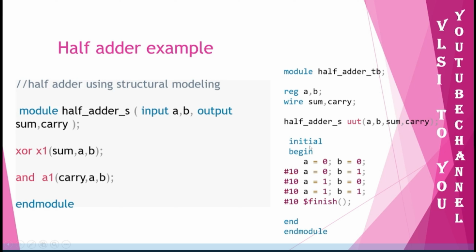Right, so now coming to initial and begin. You will be passing the values to a and b. Since a and b are reg, they will be holding the values, and a is 0. Any type of values you can pass. I am passing all the possible scenarios: 0, 0, 0, 1, 1, 0, 1, 1.